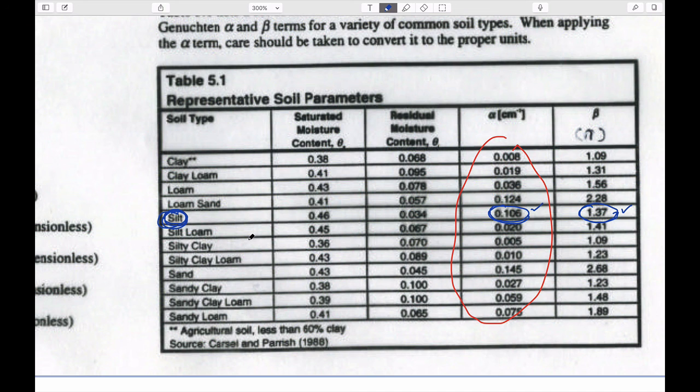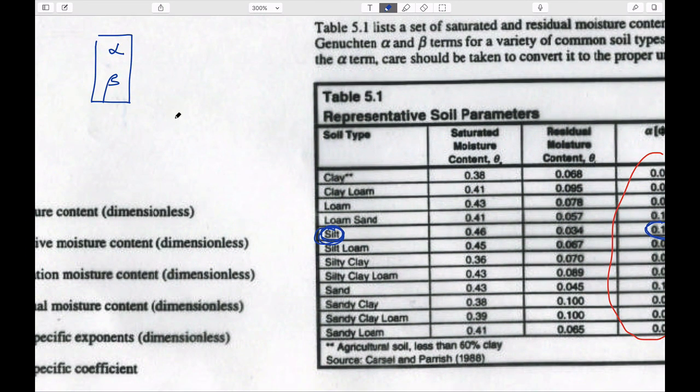Unfortunately, you can't say much about the permeability, but we did say last time that permeability could be written as, for instance, something like this. If you know the porosity and the diameter of the pores, and people often take the diameter of the grains as similar to the diameter of the pores, then it gives you a magnitude of what the actual permeability is. And if you want to know the effective permeability, it's the actual permeability multiplied by the relative permeability, which is between 0 and 1.